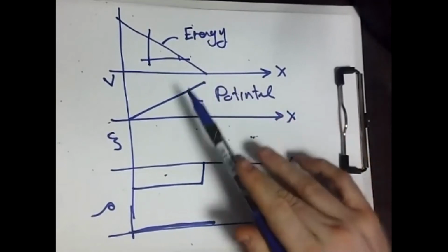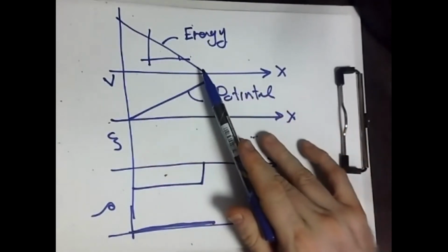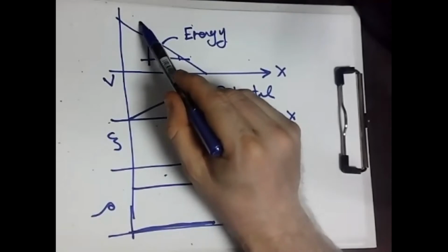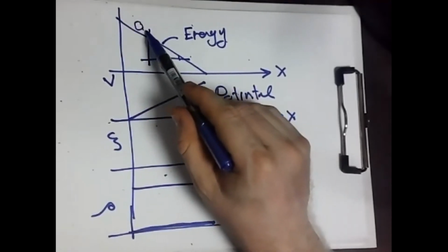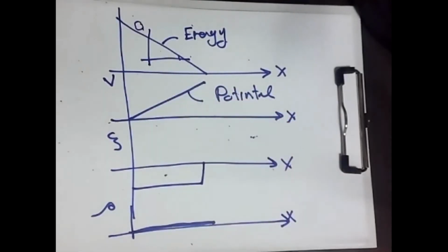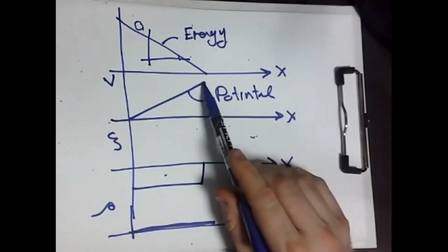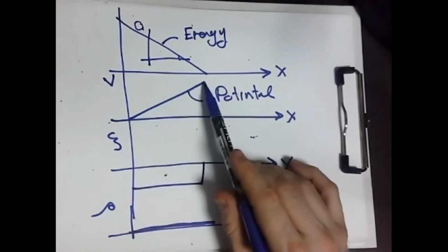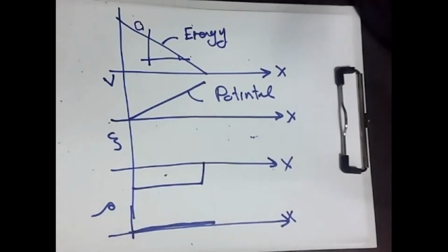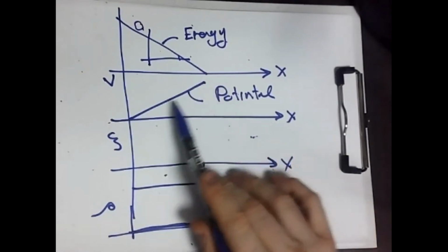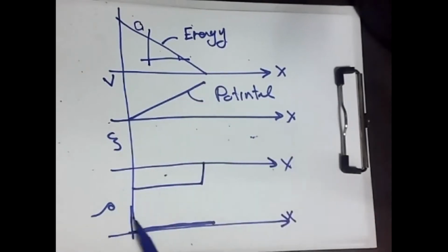First, here we understand, whenever you have this energy band diagram, if you have an electron here, this electron will drift in this direction. That's why this is the higher potential and this is the lower potential. Okay. And whenever you have a potential, then you have an electrical field. This electrical field may be positive or negative. So why is this electrical field negative? Let's try to understand.